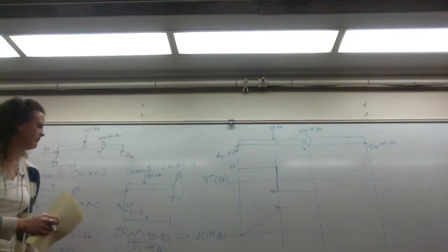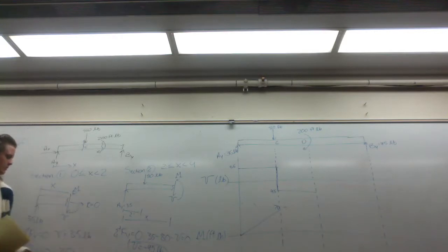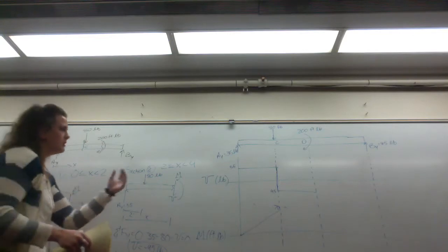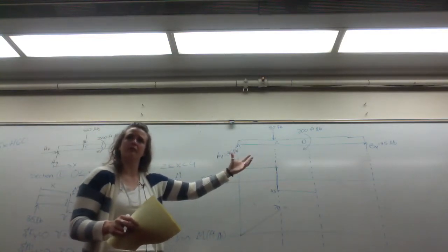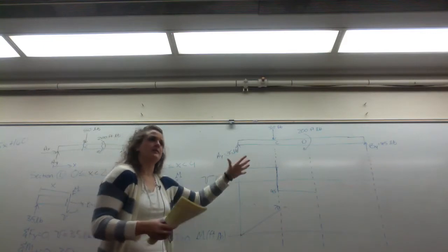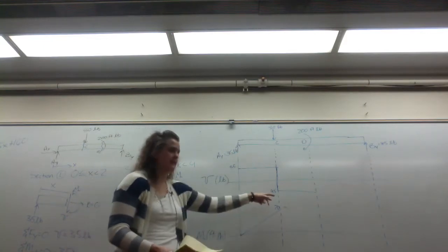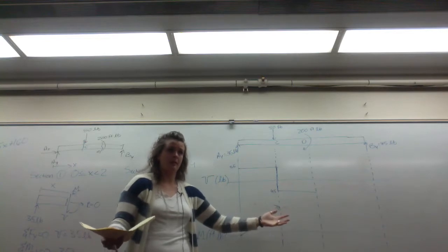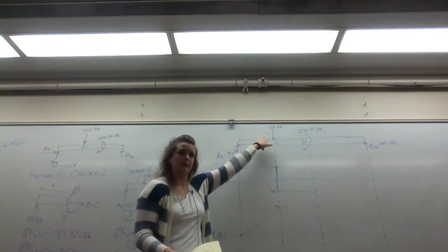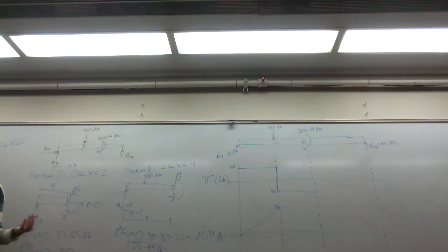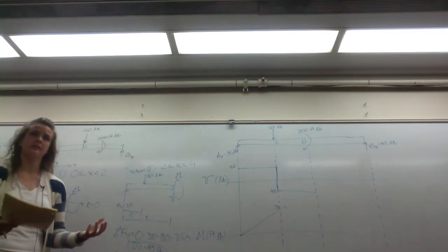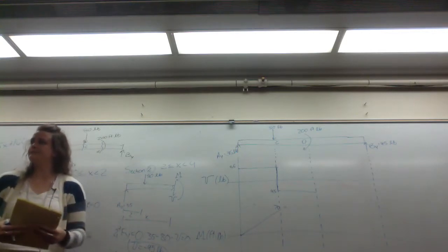We found that using this method, as we've sectioned off, but you also see this in your graph. So this is a sanity check. If we had gotten negative 65, but we only were applying an 80-pound force, check your math. So there are some sanity checks here for you to use.